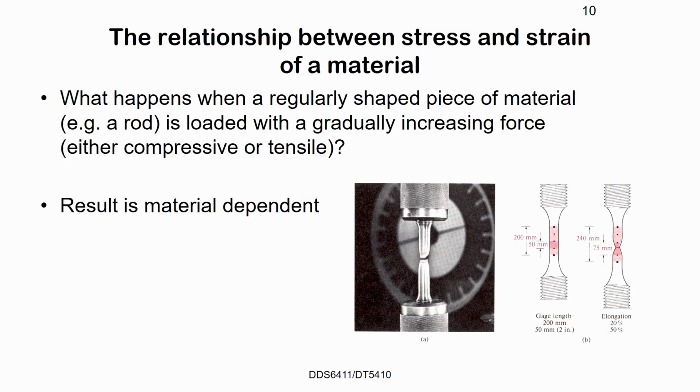Well, that's creep. Yeah, slow deformation. That's right. That's an example of creep. So when you have a heavy load, it'll eventually break. Given enough time, it will break. And you don't want to give it a jolt. It's also strain rate dependent. Everything creeps. It depends on what material it's made of, like a bridge. I'm sure you've seen old warped window glass. That's creep of the glass.